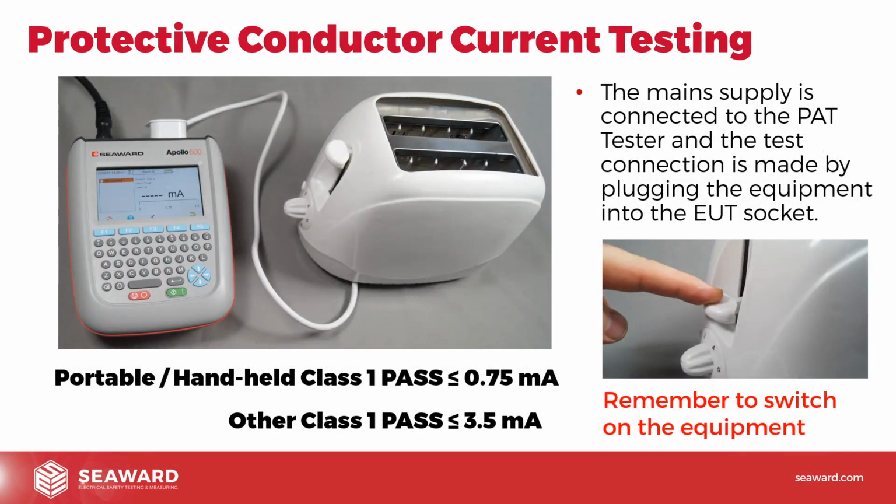Now, if we just go on to the next slide here, you'll see how we connect up the PAT tester. So you'll notice that the main supply is connected to the PAT tester, and the test connection is made by plugging the equipment into the EUT, the equipment under test socket on the PAT tester. So you can see there we've got the black mains lead into the Apollo, we've got the toaster there plugged into the test socket, the EUT socket on the Apollo, and the Apollo is going to pass that mains current through to the equipment under test, the toaster, and measure the leakage current.